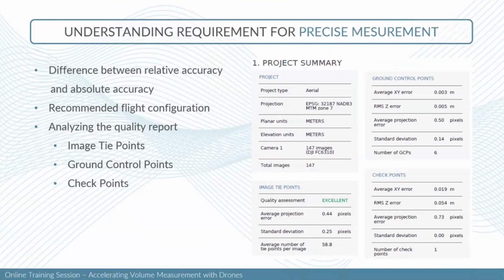reconstruction. If you want to assess the overall accuracy of your project, you may take a look at the ground control points residual. So you will have all your errors assessed in planimetry, in vertical, and also the number of GCPs. If you're using checkpoints, which I think are the most valuable source of information to validate the result of your AT, because ground control points will be used during the bundle adjustment to help achieve a better overall accuracy.